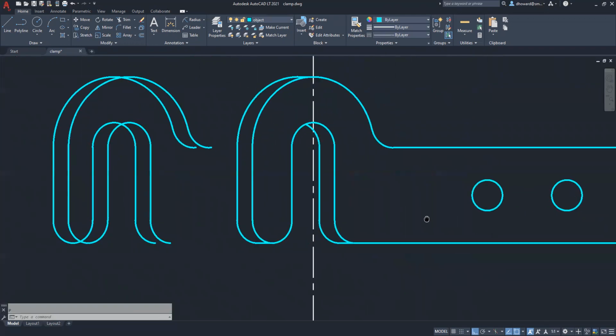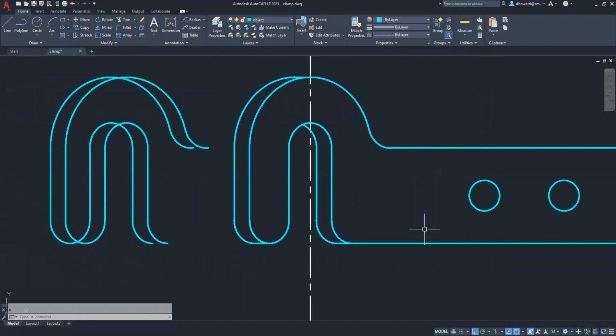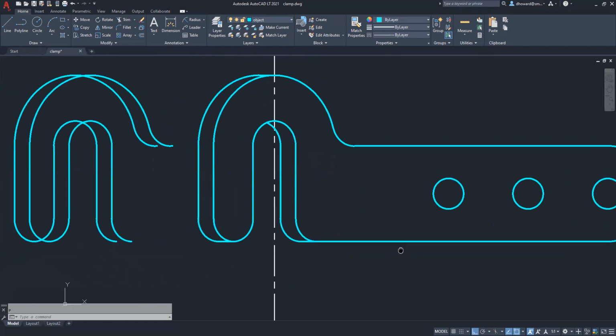Okay, so if you were just going to do object lines, you would be content with this. And a lot of people would say that's enough. That is more than enough for representing this hook. But if you really wanted to show all of its edges, you would show the ones that we just trimmed away as hidden lines.